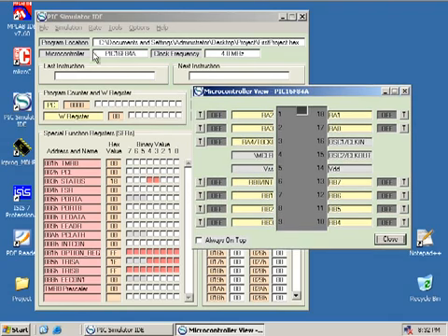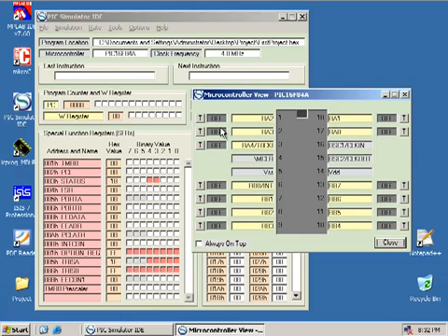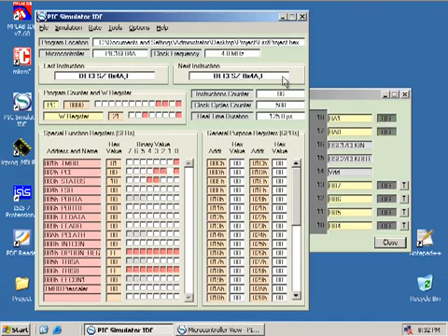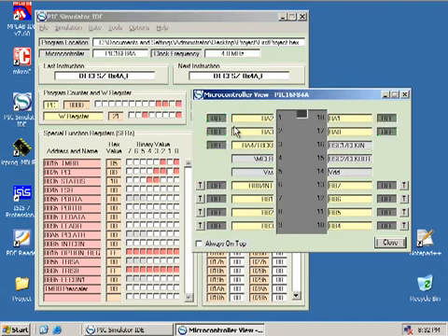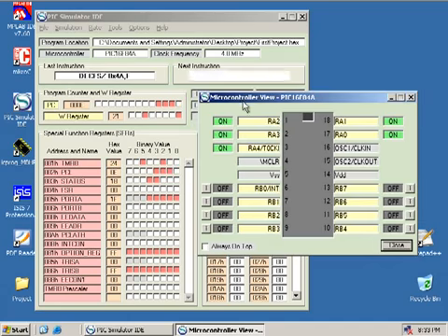and the microcontroller I have selected here is the PIC16F84A. The pin configuration, all the pins are shown here, and I can simulate my code, simulate and start. This is a very simple program, and it changes the voltage from 0 to 5 of all the port A pins of the PIC16F84A microcontroller. You can see how the voltages are changing, graphically shown, and we can easily understand how our code is working.